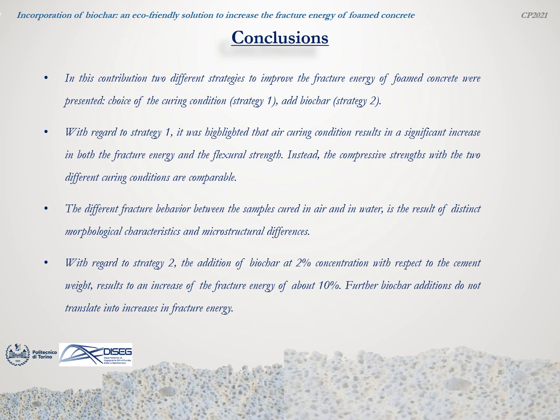In conclusion, in this contribution, two different strategies to improve the fracture energy of foamed concrete were presented. The first strategy is the choice of the curing condition, the second one the addition of biochar. With regard to strategy 1, it was highlighted that the air curing condition results in a significant increase in both the fracture energy and the flexural strength. Instead, the compressive strengths with the two different curing conditions are comparable. The different fracture behavior between the samples cured in air and in water is the result of distinct morphological characteristics and microstructural differences.